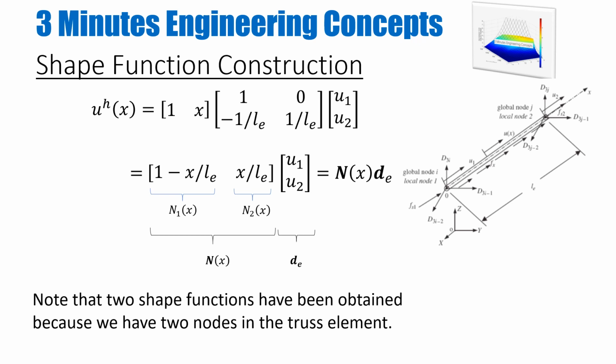So for example, if I have N1 and N2 in this slide as shape functions, then my shape function N1 should be 1 at node number 1, while it should be 0 at node number 2. And similarly for N2, my interpolation function will have a value of 1 at node 2, and it will be 0 at all the other nodes.